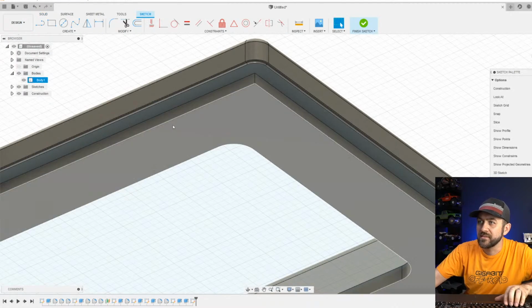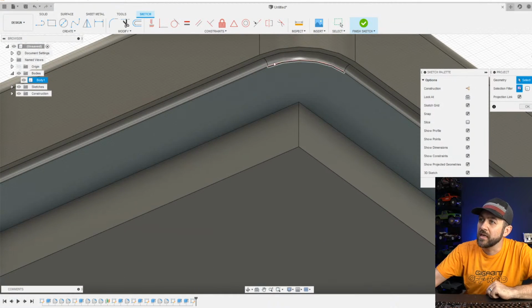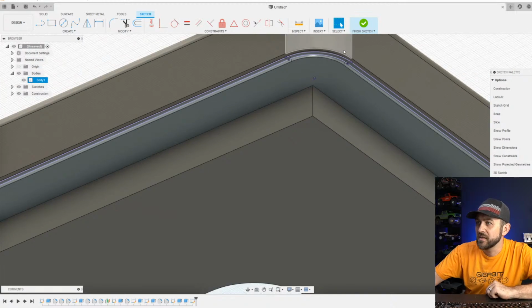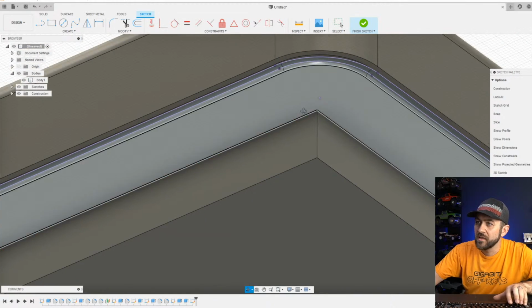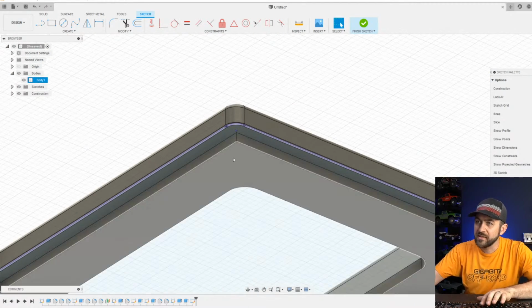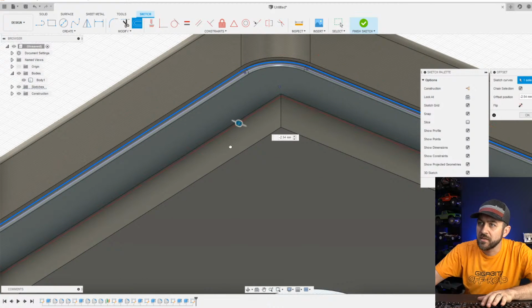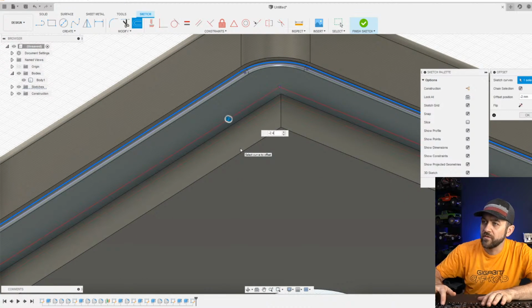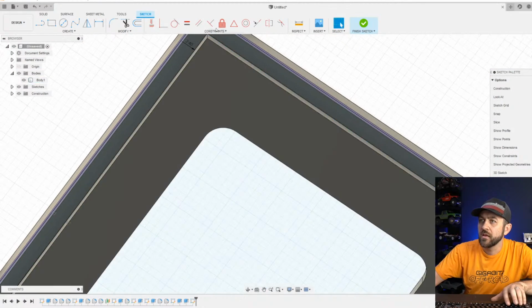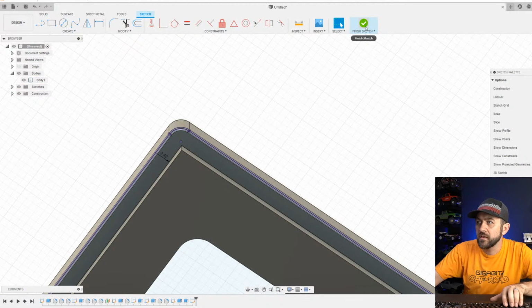So now we're going to create the second body back on that plane. We're going to create our geometry based on that surface. And lastly, I'm going to offset that outside surface -2.4. So that puts us right where we need to be.